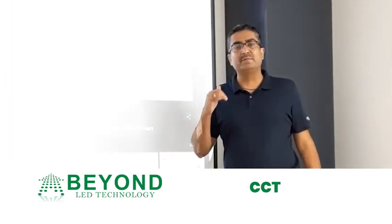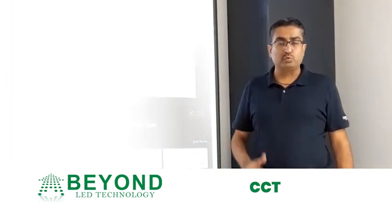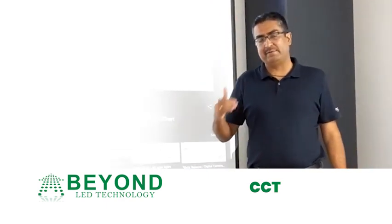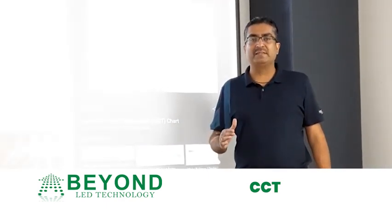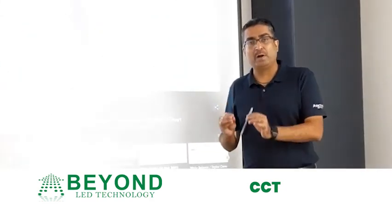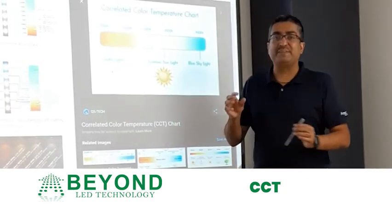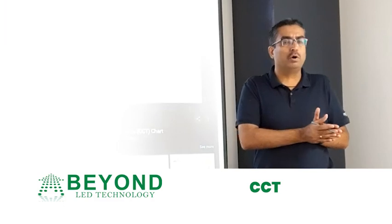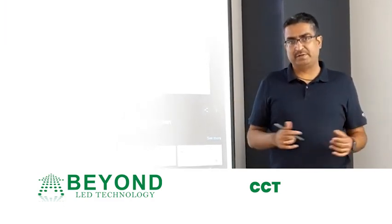The maximum color temperature to be qualified for DLC under the indoor lighting category has to be 5000K or lower. For the outdoor lighting requirement, the product cannot be higher than 5700 Kelvin. So 5700 Kelvin or lower can be DLC or Energy Star.